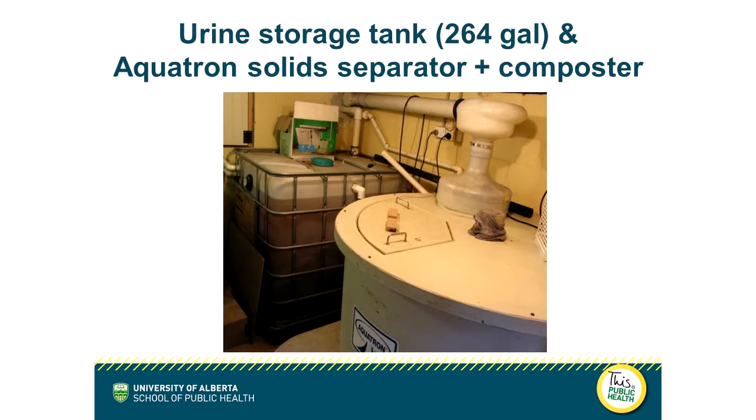And this is a greywater treatment system, to give you an idea. These look like they're about the same size as 2 to 3 household refrigerators, commercially available in various parts of Australia and other regions of the world, that can treat your greywater to a non-potable, high enough standard to wash your clothes, irrigate your garden with, and flush your toilets with. Okay. That, by the way, is the composter underneath my dining room table.